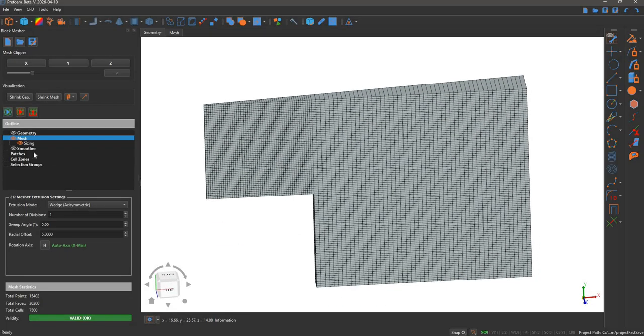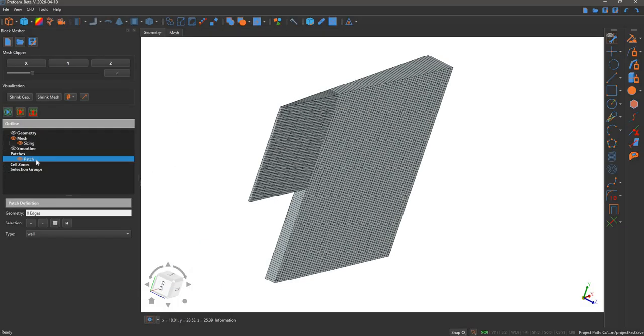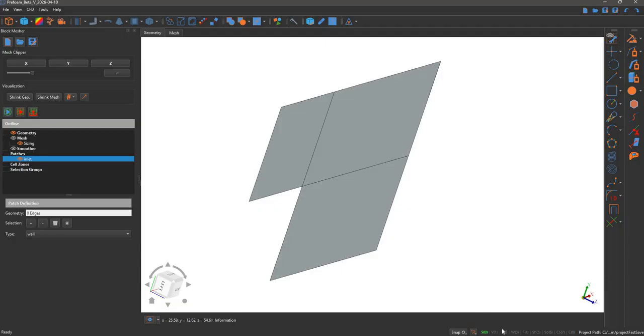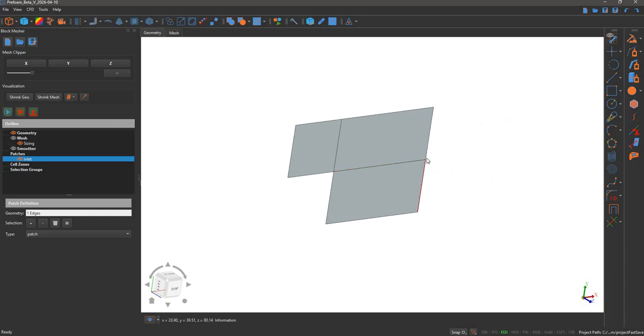The patching and exporting are just like in the other videos. In the airflow video we show that we can create a patch and rename that as inlet. Then you need to select edge, turn on the geometry again, turn off select edge from here, hit that, and that will be the patch inlet, and you need an outlet also, like these two.